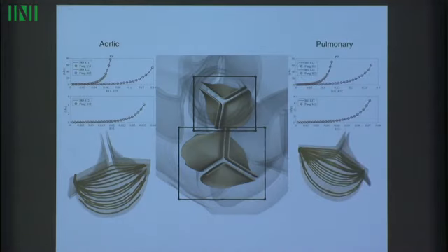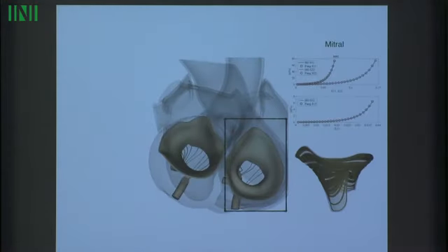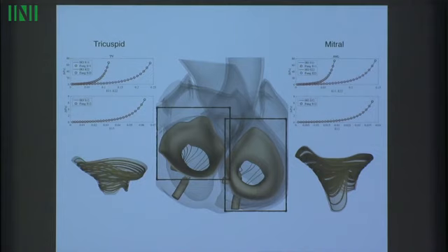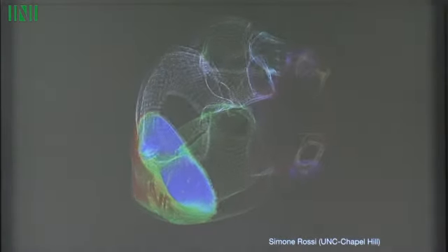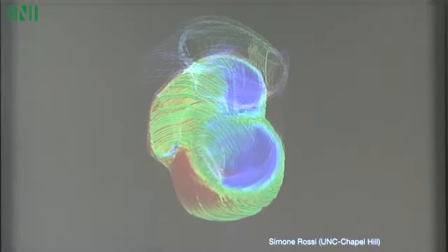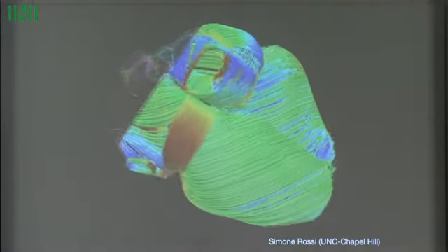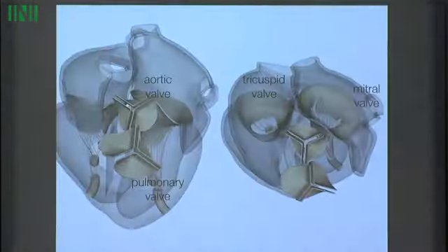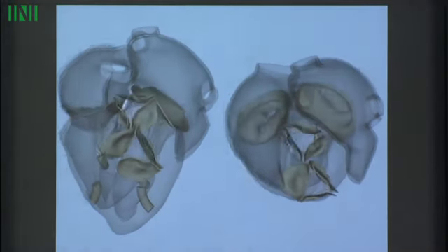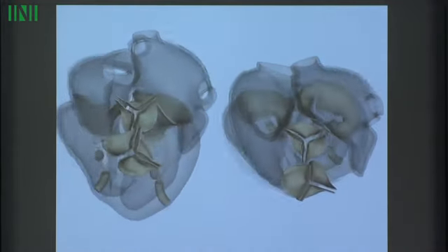So we've put together models of the heart that include pretty realistic descriptions of the biomechanics of the valve. So these are still hyperelastic models that have, sorry, I shouldn't say that, have homogeneous material properties. They're anisotropic. Fiber model of the heart that includes the ventricles as well as the atria. And putting this all together, have some initial simulations of fluid structure interaction.